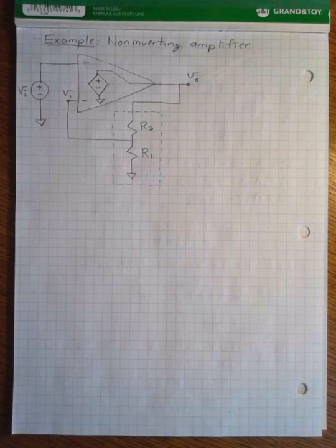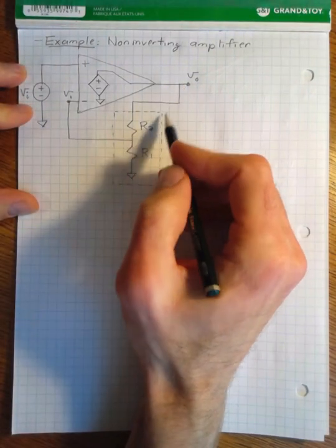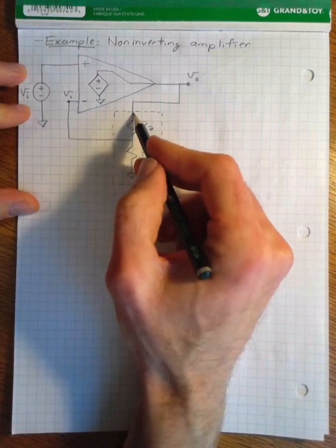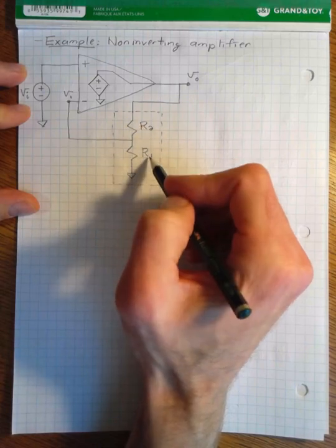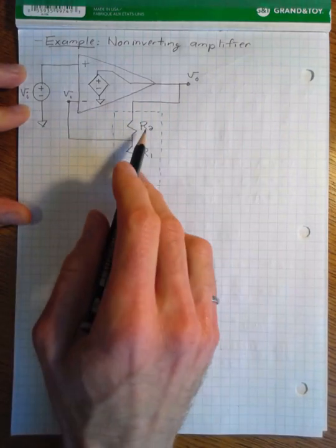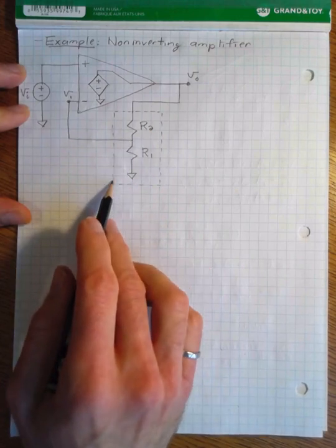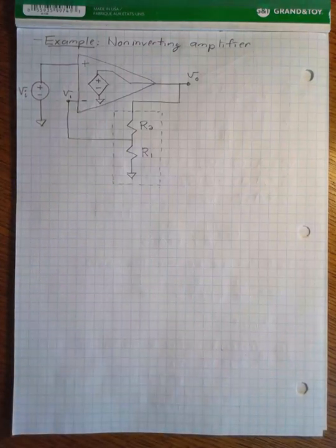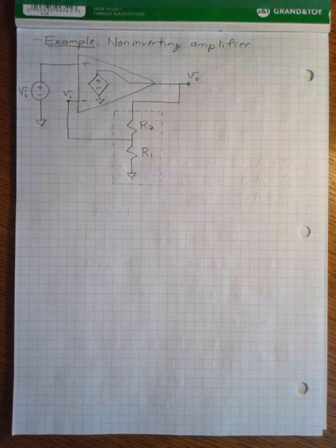Okay, so here is the non-inverting amplifier using the feedback analysis that we've developed. The first thing to note is that I've replaced the box with that beta factor by a voltage divider, a couple of resistances R1 and R2. Now, this voltage divider is basically exactly equivalent to the resistance network that we had hooked up to our non-inverting amplifier at the very start of this module. And if that's not clear, you must convince yourself of that before going any further.